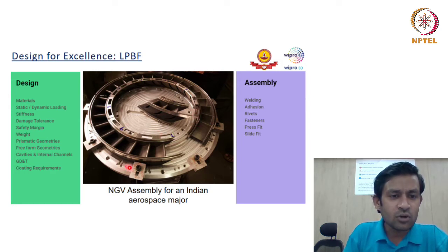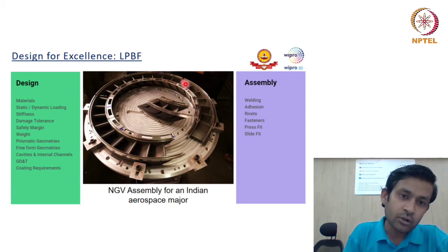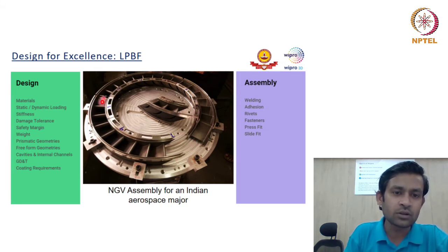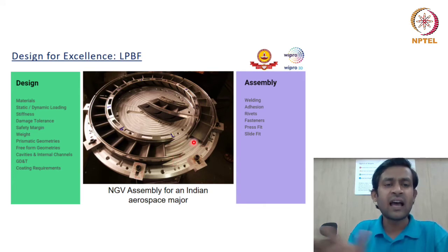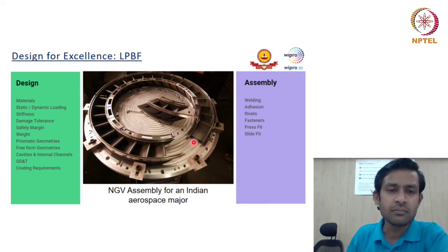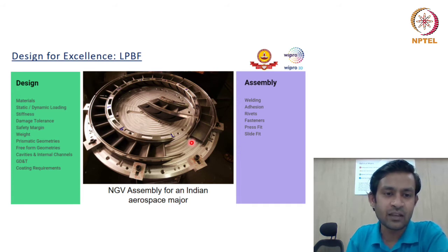Why? Because the component had to mate into the assembly, and in order to check that all the mating features had been machined properly, a fixture was used. The fixture had similar mating tolerances as compared to the original assembly conditions. Therefore, we were able to evaluate each and every point where machining is required. We added stock there, and later on we machined them together.